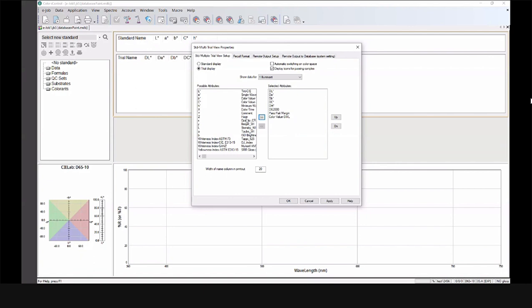And then haze measurement. If we are doing haze measurement and we want to check what the haze percentage is, it will give this. We will refer to this value, which is in percentage, and based on that we'll check. If the value is more than 95, then we'll say that the material is near opaque or opaque. If it is around 70, then we can say the material is translucent. If it is less than 30 or 20, then we can say the material is almost transparent.